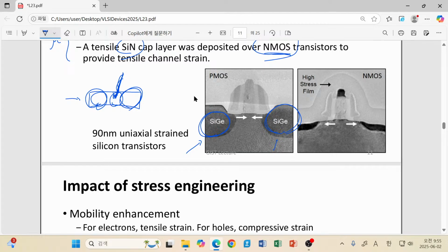The central one feels certain stress from these two surrounding big guys. That happens to our silicon channel, and when our silicon channel is compressively stressed, it is known that its hole mobility is increased. So that is the main reason why we get improved hole performance.